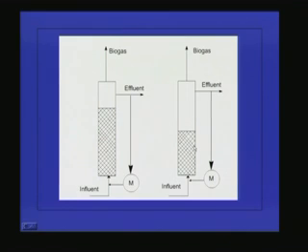There is no clear-cut distinction between these two, but if you see the expansion, if the expansion is less than 30% of the original bed height, then we call it an expanded bed reactor, and if the expansion is more than 30%, we call it a fluidized bed reactor.